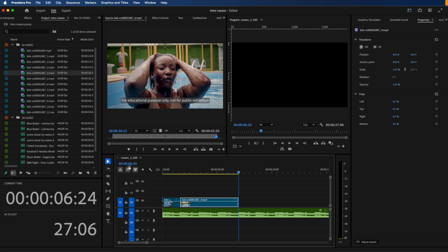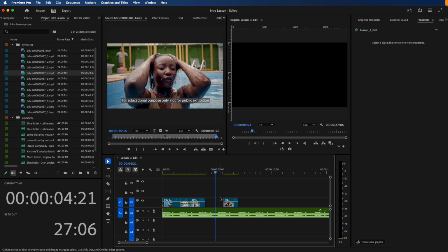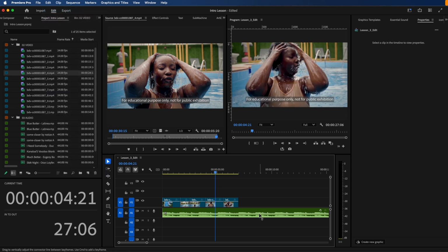And also the next important tool that we're going to be working with is the cut tool. You can select it and use it to cut anything you want, right? So I can just take this, cut this part, go to the move tool, select it, and then if I press delete on the keyboard, it's going to go. And if you accidentally delete something like this, you can always undo it by going to edit, undo, and the shortcut key is Control or Command Z.